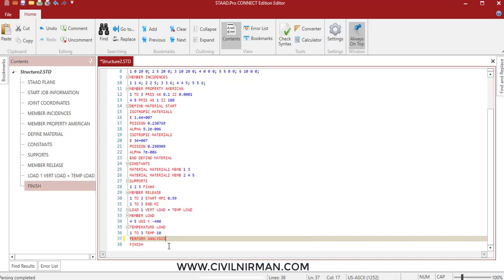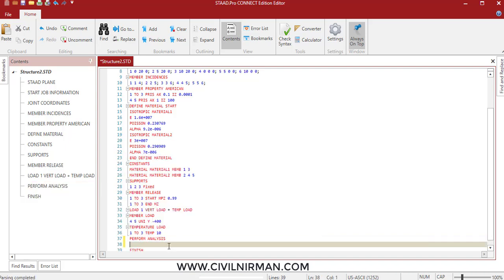So I'll enter the command as perform analysis, and then we want to get the stresses for a particular segment. So I'll enter the command as print member stresses, and we will list out the members, list 1 2 3, right?